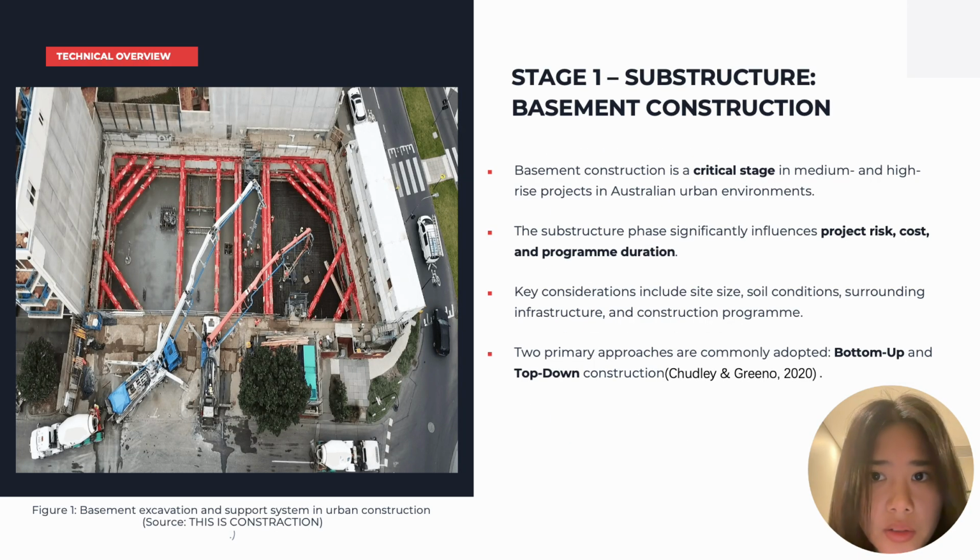The basement construction is a critical stage in high-rise projects. It directly affects project cost, risk, and construction time. The main factors include site conditions, soil type, and surrounding buildings. In Australia, two main methods are commonly used: bottom-up and top-down.